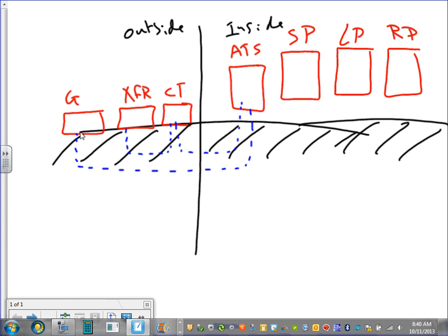So you're going to take a feeder from the generator, the transformer, to the auto transfer switch. The auto transfer switch will select which power is available, and it's going to dump the power into the meter, into the main panel. From the main panel, you will be going first to the lighting panel and second to the receptacle panel. This is how the power system in this commercial building is going to be distributed. That's your riser. Cool?